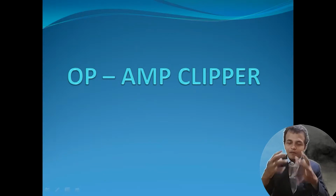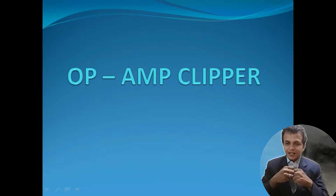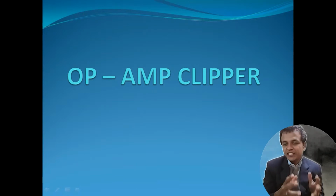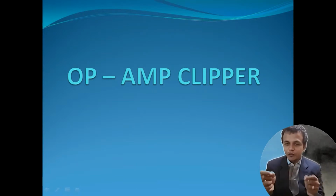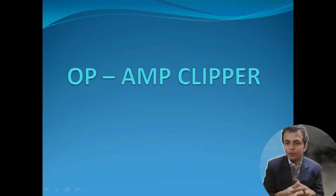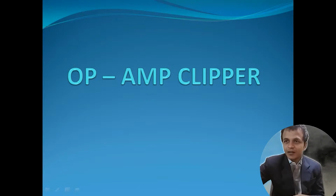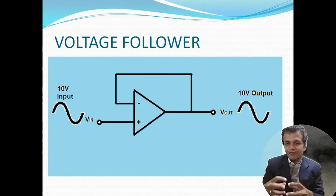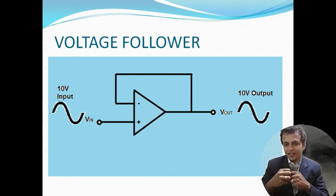So from where does this clipper arise? As I mentioned, apart from the clipped portions of the signal, the remaining portions remain the same. There won't be any change. So basically it should be a voltage follower circuit, because the remaining portions are the same. The output voltage is the same as the input voltage for the remaining portions. To this voltage follower circuit we have to make certain changes, and according to the changes we make in the design, the clipping operations are done.